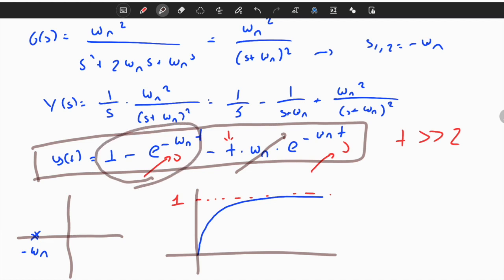From this perspective, you can understand that a critical damp system acts like a first order system. And believe it or not, it's a good thing. The second pole is going to 0 faster than the first pole. It becomes approximately a first order system. If you, for example, perform a system identification or some sort of analysis, you may even assume that the system is a first order system, because it's very close. The double root case or critical damp case acts like a first order, especially after t passes the time constant of the system. So this is the basic idea.